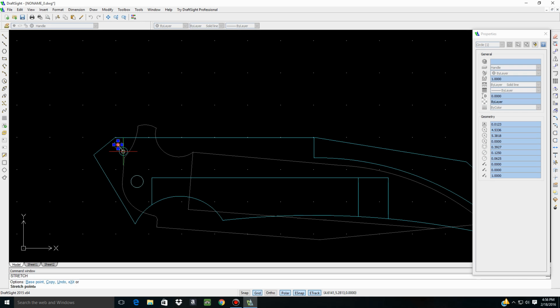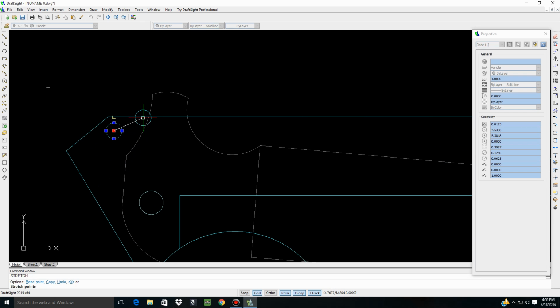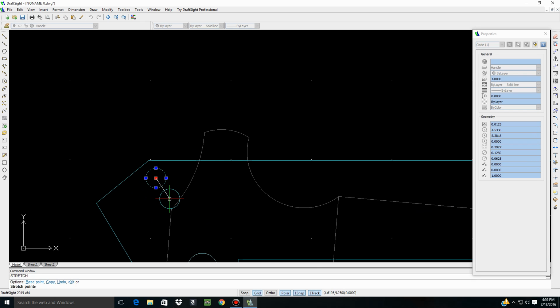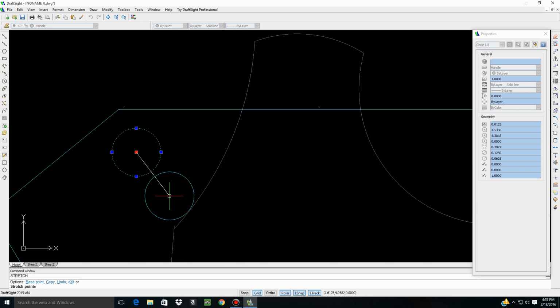Some guys like to cut out a little notch or something like that, and we could do that as well. This way you don't have the exposed flipper when it's down here, or a notch in it, or some wear marks from a stop pin. So let's put it just so it's touching. Let's call it right about here.